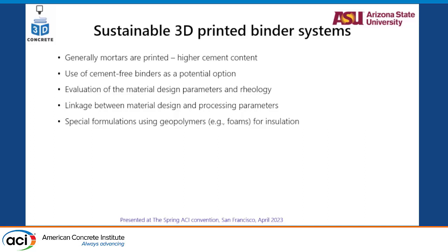A lot of our work is in the zone where, yes, materials are important, but materials are always linked to the processing parameters. If you don't take the processing parameters into account, for example, if you have two printers in your lab, you will notice that what you can print well with one printer is not something that you can print with another printer with a slightly different nozzle characteristics, a slightly different pushing mechanism, whatever that is. So processing also becomes very important.